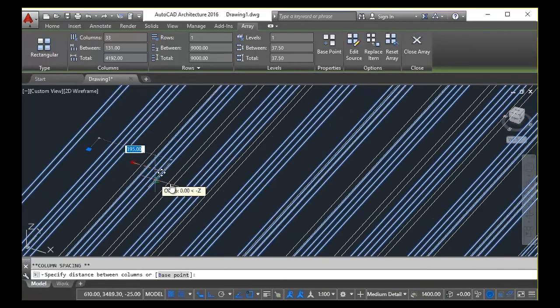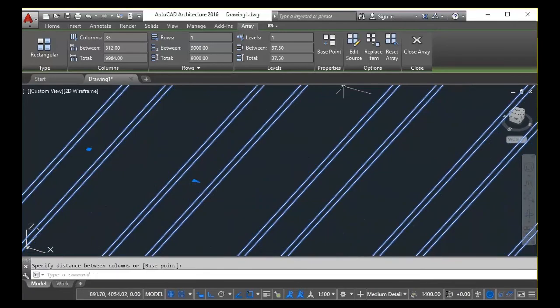Now notice when I change the distance that this value here changes, which is the distance between. So if in your case you want your floorboards to have a little space in between, then you can just edit that distance, or you can use the little arrow to eyeball it. Alright, so in most cases you may want it to not have anything, any distance, so you put 0.